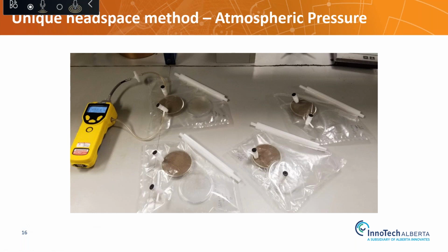So that was a bit of a unique design that was developed, and it also has this clamp, so we could put the petri dish with the spiked soil inside, suck all the air out, clamp it, and then add a known volume of headspace, so you would know what kind of VOC evolution you'd get into that known headspace. Monitor with PID, take the GC samples, and identify what kind of VOC concentrations you would get, and then plug those essentially into the model that accompanies that trench scenario.